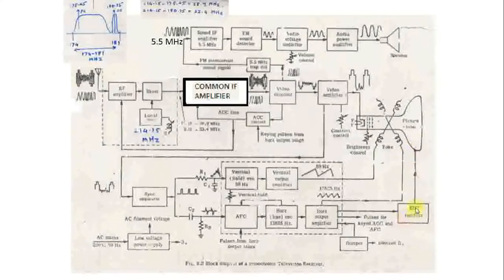So if your television is 14 inch, approximately 14 kilovolt is generated. If it is 17 inch, approximately 17 kilovolt is applied at the input of the final accelerating anode. And if you go for 25 inch and above, normally 33,000 volt and so on is required as EHT voltage. I have already explained in my lecture how black and white television works. Thereafter we will move to color television.